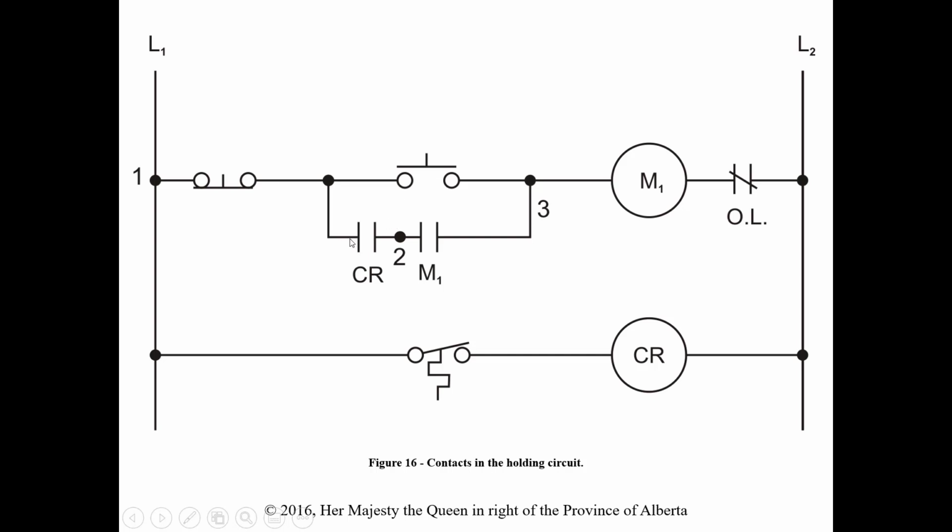But if this control relay is closed, I press start and I'm running through the hold circuit now, because when this is energized, this closes. If this is closed as well, then I'm running through the hold circuit at that point. Now, if I'm running and this control relay opens this set of contacts, then I will stop it. So it does affect the stopping, not the starting.